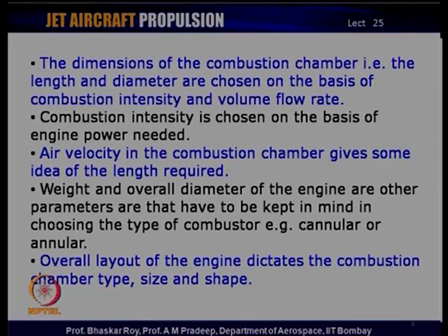Now, if you look at the dimensions of the combustion chamber, the length and the diameter of the combustion chamber are often chosen on the basis of combustion intensity and the volume flow rate. Now, the volume flow rate into the combustion chamber is decided by the engine airflow rate, and the engine airflow rate is decided by various parameters like what is the thrust requirement, and so on and so forth.